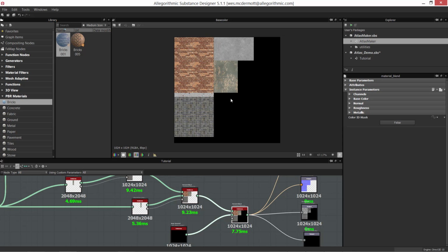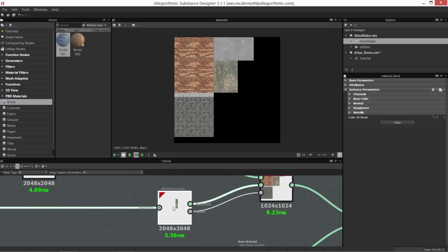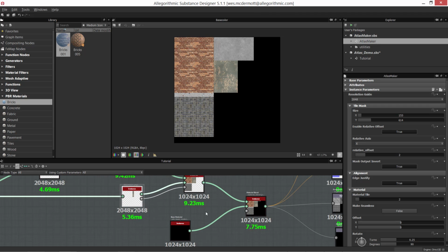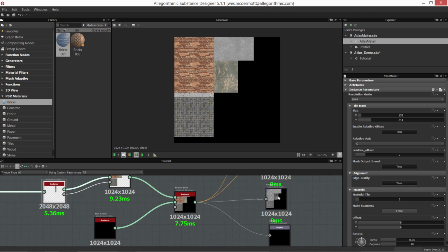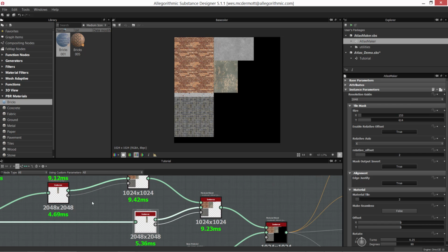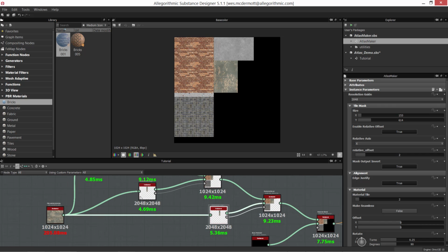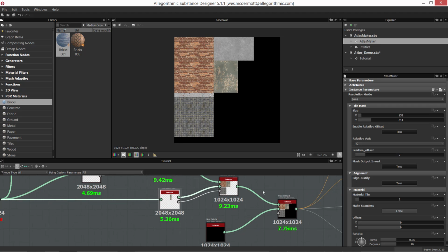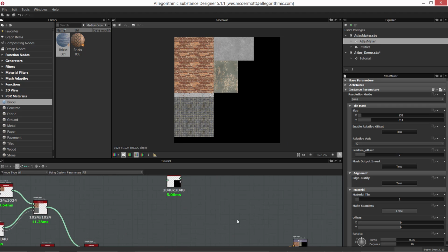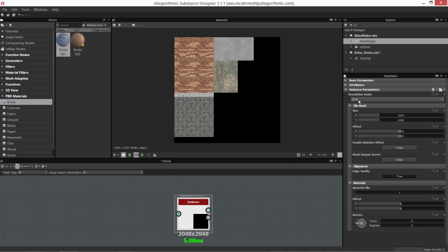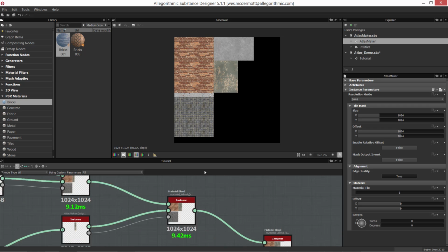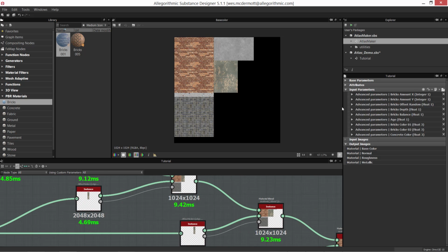Well, if I let the atlases stay at 2048, and here's one of them here, you can see the situation you can get into where the final output's going to be 1024. Most of the nodes are processing at 1024, but all of the atlas nodes are processing at a higher resolution here. So this becomes an unoptimized way of working. That's why you would probably set this resolution guide to whatever that max resolution is going to be. Notice here, I didn't set these at 4K because I'm not going to do a 4K output. I'm only going to do 2K as my maximum.